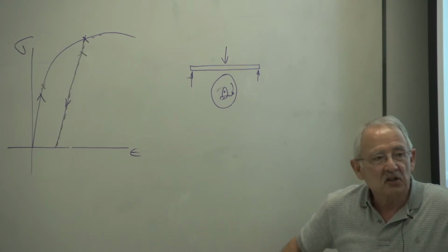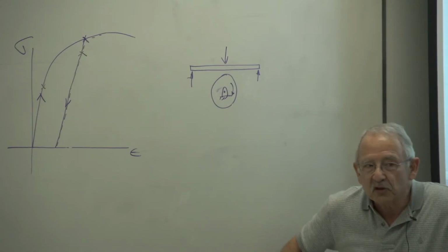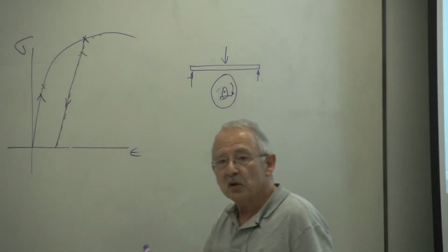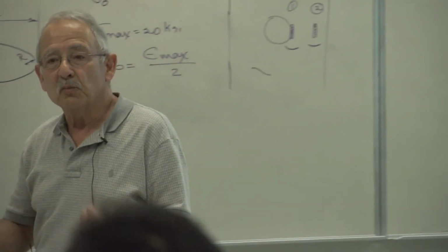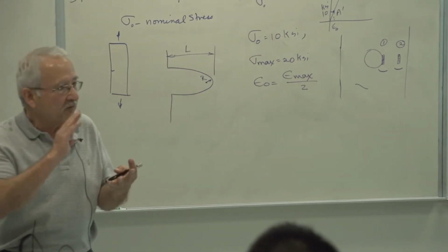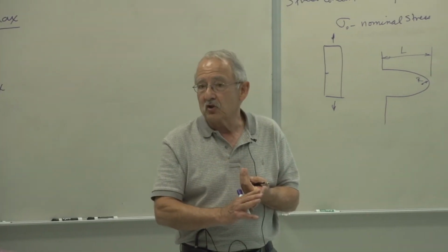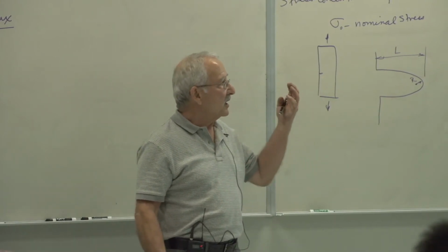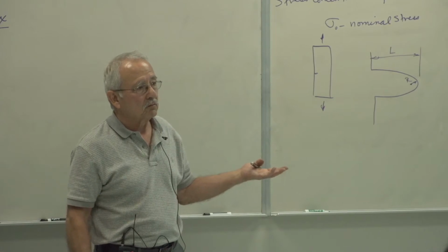It doesn't matter that the stress in it may be 1 ksi, or the strain may be very, very small. So long as it is not able to perform the function for which it was designed, the part is assumed to have failed. Now, this can come from yielding, it can come from fracture, it can come from undue deflection, permanent change of length, what have you. So failure is the inability of the material to perform the design function, period.